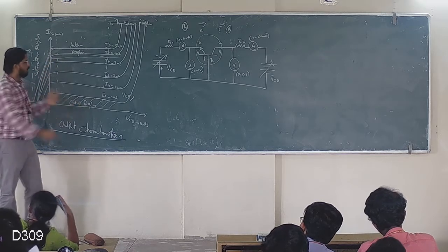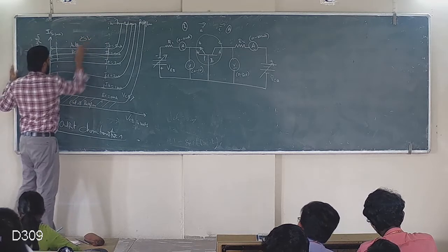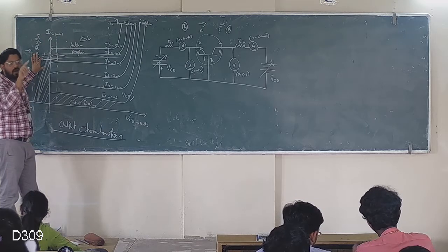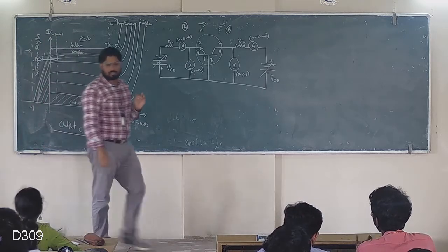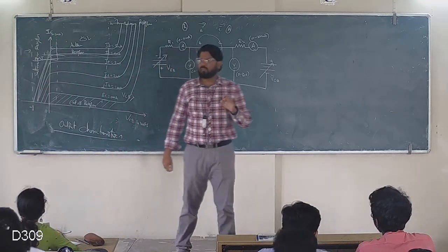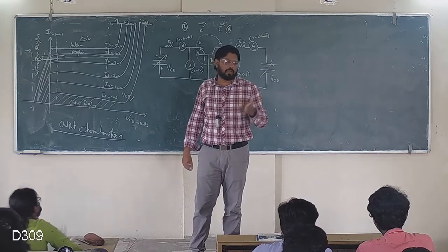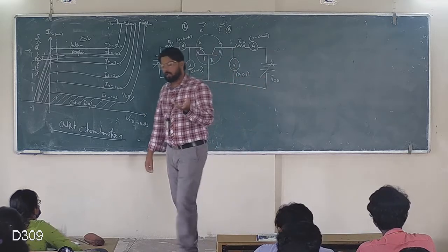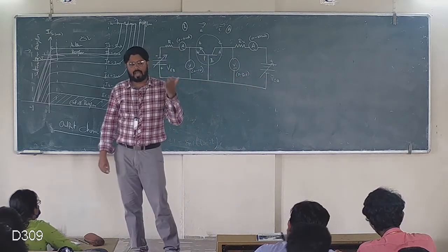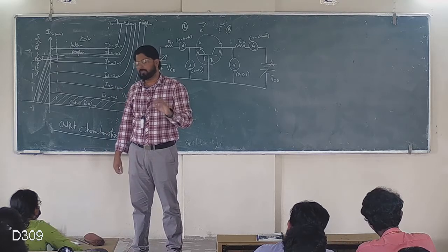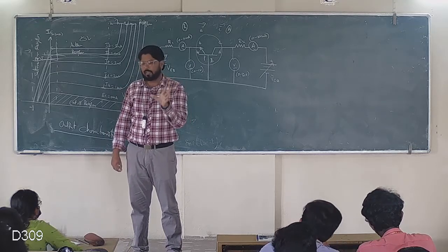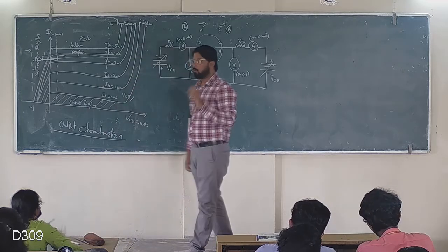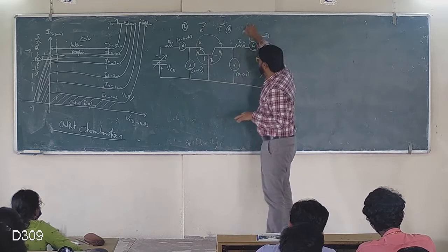Change in dV with a change in dI: dV by dI equals small r. What is small r? Dynamic resistance. Smaller letters, in any circuit theory or electronics book, irrespective of the author, are notation closely associated with omega, meaning a change in the AC signal.